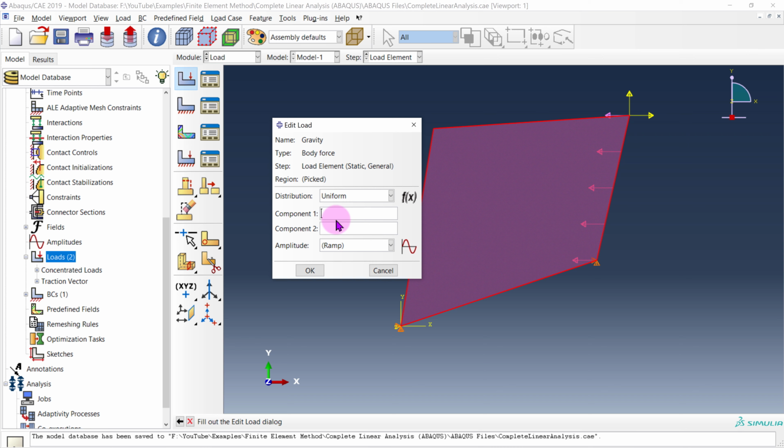So a good example is what I did in my assignment for my students: I gave them a density of 2400 and I gave them a gravity load of 9.81 meters per second squared. So if you were to do this in the assignment using the gravity command, then in the density you'd put 2400, and then in the gravity command you would put 9.81. But if we're doing this body force command, what we'd actually have to do is take that 2400 and multiply it by 9.81. So basically in this command right here, we have to figure out the body force, which is going to be rho multiplied by b. It doesn't matter, you can do it either way, you're going to get the exact same answer, but I'll just keep it as a body force because I have it opened.